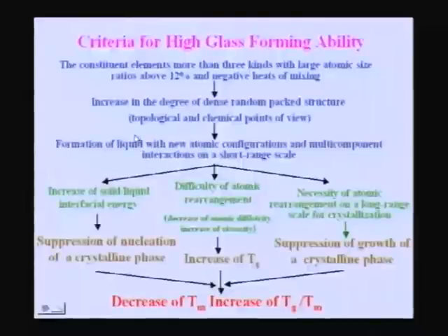As a result, you end up with new types of liquid, liquids with dense random packing and good short range order, multi-component liquids with good short range orders. Such liquids will result in an increase in the solid liquid interfacial energy, and if the solid liquid interfacial energy is high, then the formation of the crystalline phase is more difficult.